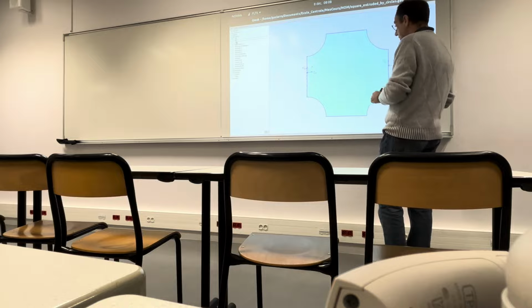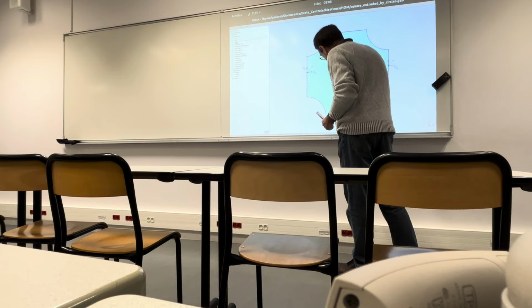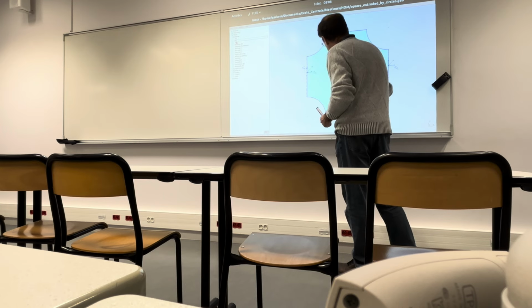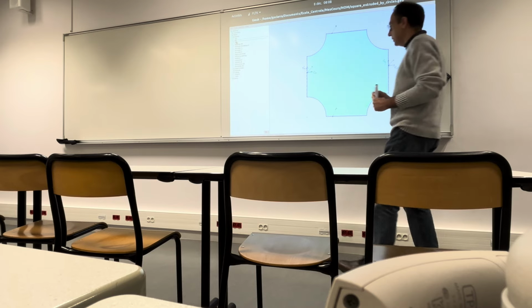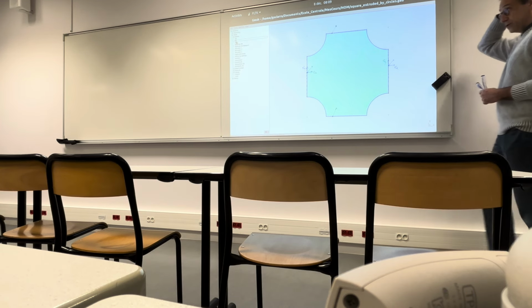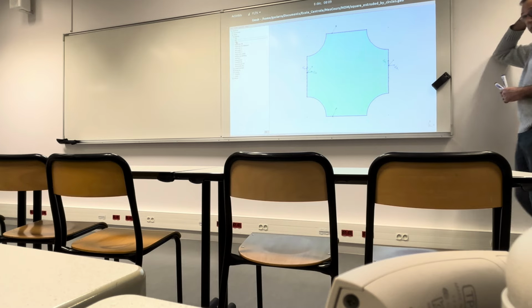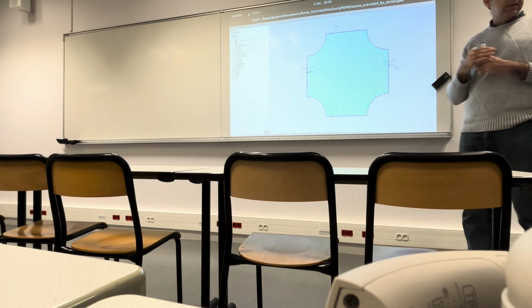The same at the top and the bottom. So if I stay here and I have this velocity field, I should get exactly the same at the corresponding point. So these are purely periodic boundary conditions, so we are not going to prescribe values, but just the periodicity property.